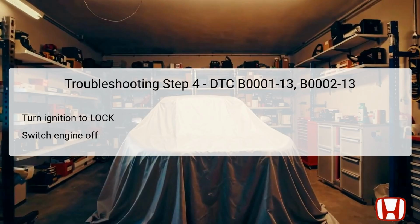After assessing the presence of DTCs, the next step involves turning the ignition switch to the lock position. This indicates a move to off mode, effectively shutting down the vehicle's electronic systems. This critical action is necessary to ensure safety while working on the airbag system, as it mitigates the risk of accidental deployment during subsequent procedures.